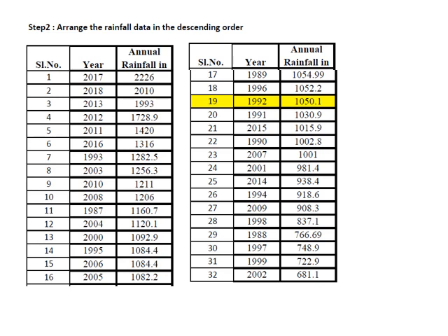So 60% of the total number of years of data collected. That means the number of years of data collected is 32. So 60% of 32 comes to around 19. So serial number 19, that is 1050. That means you have to design the bund for this particular rainfall. This dependable rainfall means 1050 millimeters of rainfall is coming for 60% of the years, that is, for 19 years out of 32 years. That is what it means.